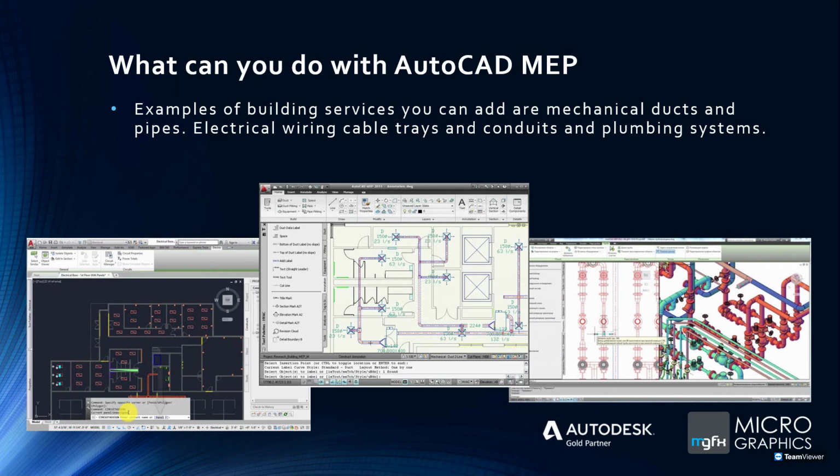Right, so now examples of what you can add to this building using AutoCAD MEP is mechanical ducts. If you look in the middle of those three images, you'll have the building with certain rooms, and you add diffusers and connect them with ducts and various other components. Right, these are object-based, so they're not lines that you offset and create. They are components and ducts and fittings that you add.